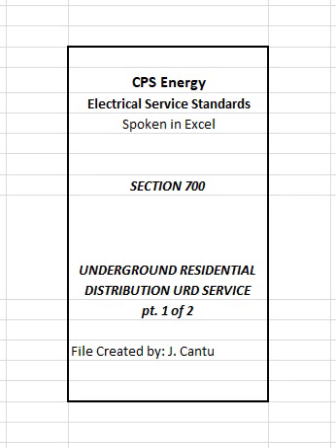1. Primary voltage cables in conduit furnished and installed by CPS Energy. Exception: with prior CPS Energy approval, customer may elect to use contractors to trench and install conduits. The contractor shall coordinate with the CPS Energy customer service representative to have all necessary inspections before covering or pouring. Refer to helpful numbers on back of front cover page.